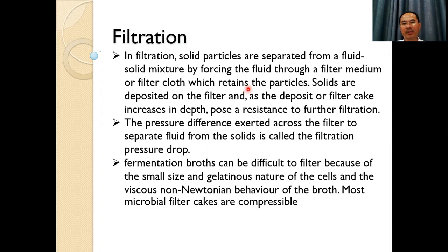In terms of function, filtration separates by forcing the fluid through a filter medium or filter cloth, with the solid retained on the filter cloth while the liquid passes through. Mostly the solid will deposit on the filter, and we call it filter cake.